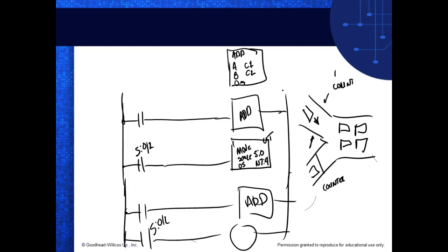And you can, because remember, it does inputs, logic, outputs. And then it goes to the next rung. So all you've got to do is just save it before the next add instruction, and you'll be fine. Just make sure the rung is between the two, right?